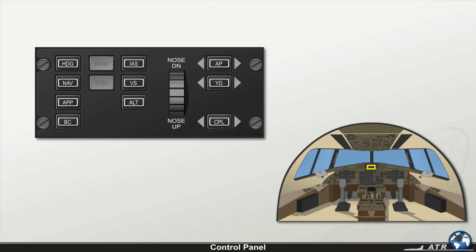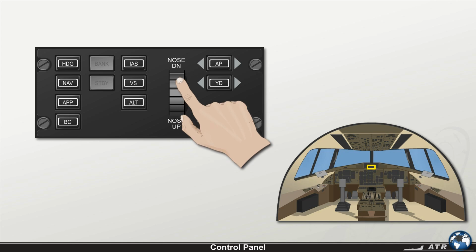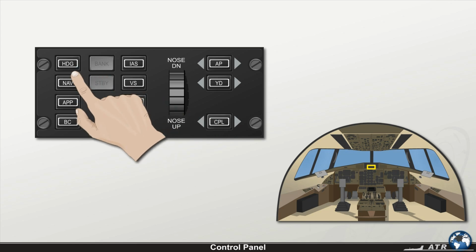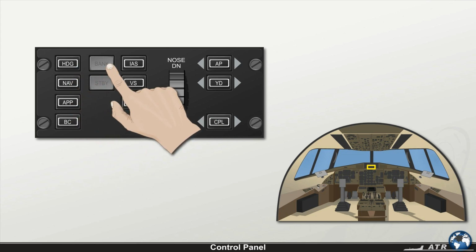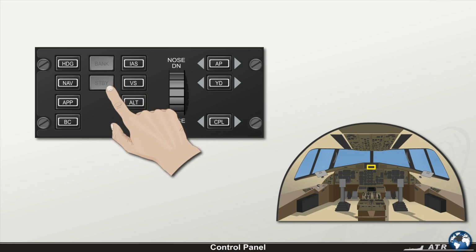The Automatic Flight Control System control panel enables the crew to select the autopilot and yaw damper on and off and select which side, captain or first officer, is coupled to the autopilot flight director computer. Select the vertical modes and adjust the desired vertical speed or indicated airspeed. Select the lateral modes and the bank angle limit. Cancel all selected flight director modes.